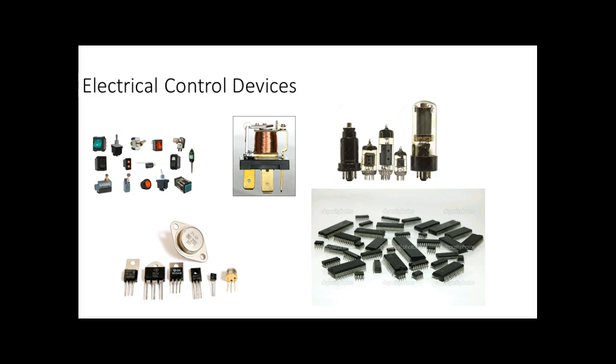But what we could do with this is dynamically control the flow of current. So these guys act like a big old rheostat, but instead of you turning the rheostat knob, we control the resistance of the tube electronically. But we do it with an electrostatic field. But these guys here required a lot of voltage. They ran off a lot of heat. They needed to generate heat to generate an electron cloud. These things used to run on about a 250 volt supply, which made them very dangerous. We had to heat them up, so they consumed energy when they were just sitting there.